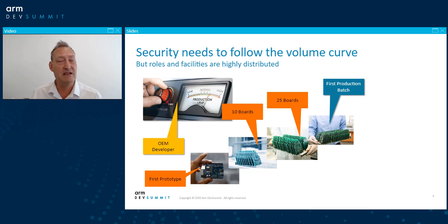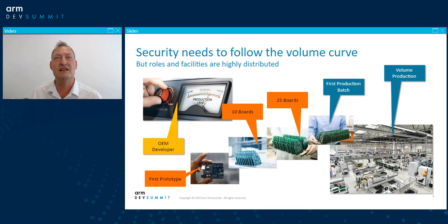And then the big day comes where we first start production. This will be with a contractor typically, and they may make some first articles for us to test, perhaps 50 pieces here, so that we can get those back in-house and make sure that production is going to be good. And then, of course, we finally hit mass volume production. Here we have that external contractor, who may be geographically separated from us, with volume production machines. Here we're typically talking about programming up chips that are then mounted on boards afterwards as part of the manufacturing process.